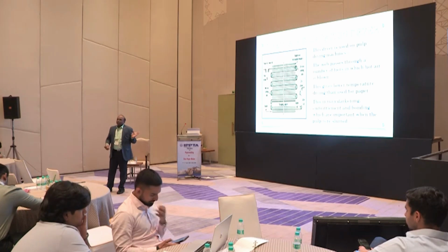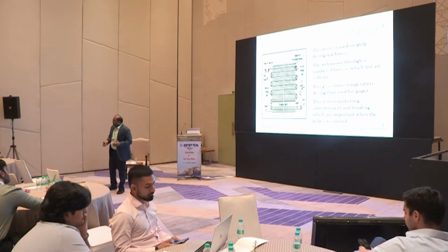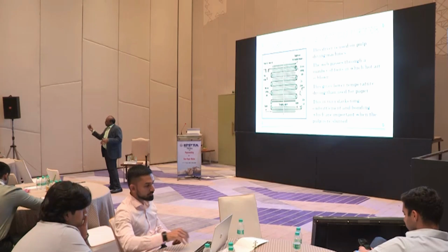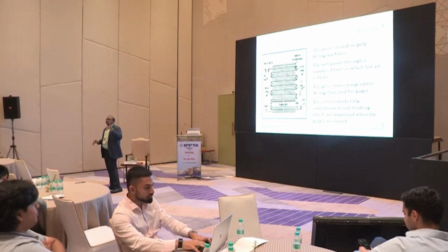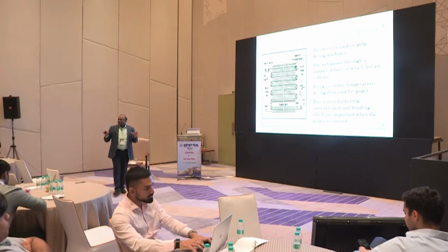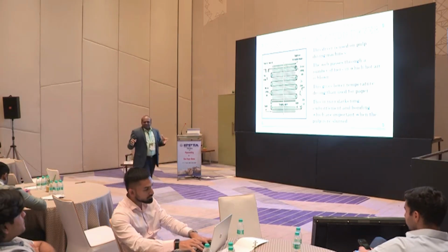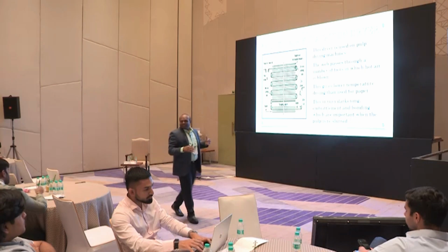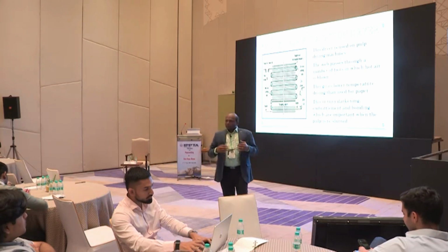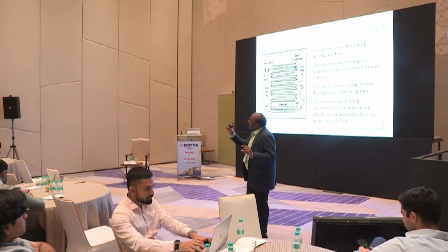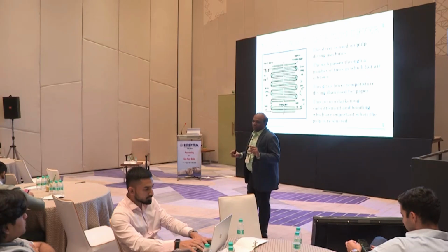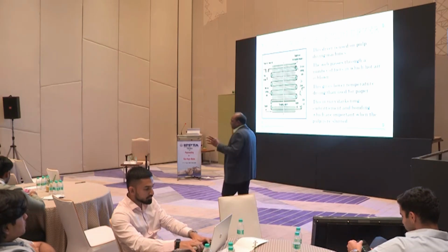For example, from morning we are discussing the raw material need. Instead of that we can procure from foreign countries as pulp, but since pulp is a fluidized material, it can't be dumped into a container and transported with high moisture. So we have to remove the moisture. For that purpose the pulp is made in a very high basis weight, for example 300-400 GSM.